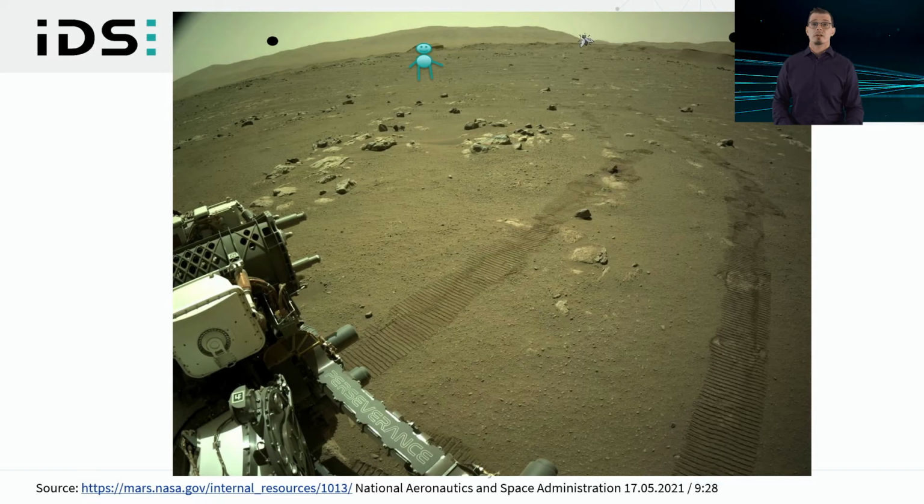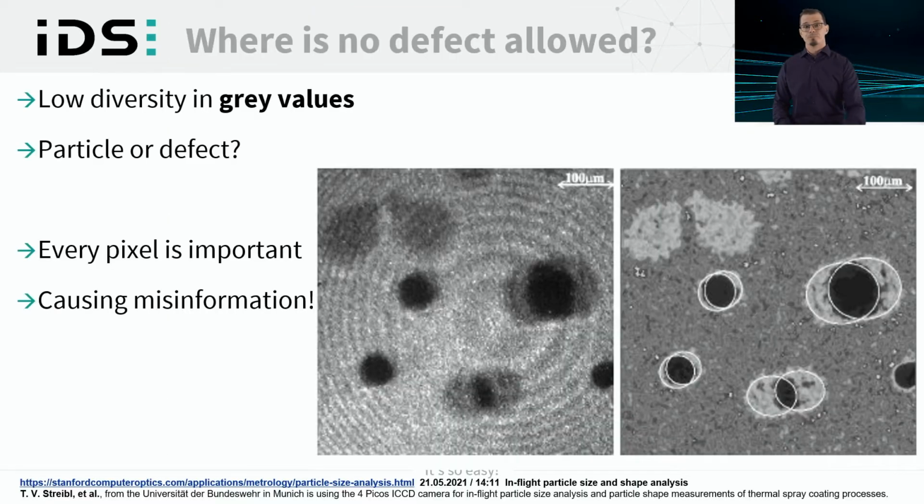To prevent our customers from such effects, it is important to understand what cleanliness of a camera means and what is needed to provide high quality. At first, we want to explain what the critical applications are. In applications which provide only a small difference between different gray values, a defect may have big effects. Images with a very uniform contrast gradient are also critical. A good example is a picture of a flower field compared with a white wall.